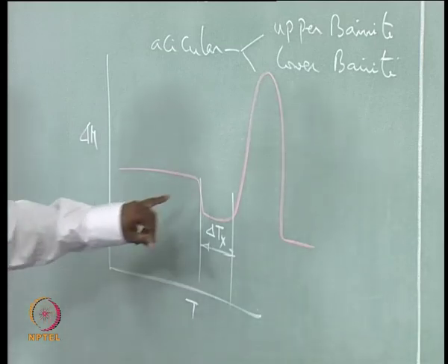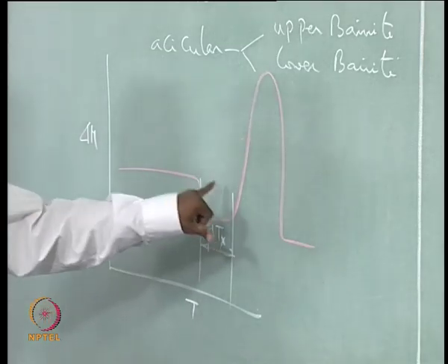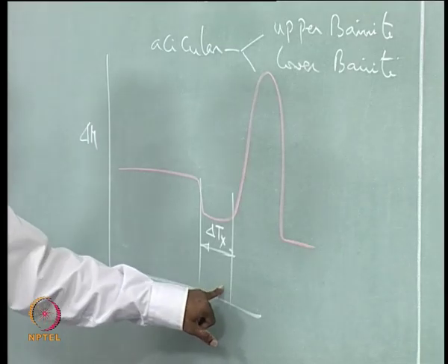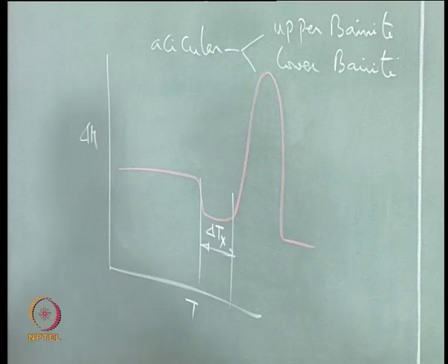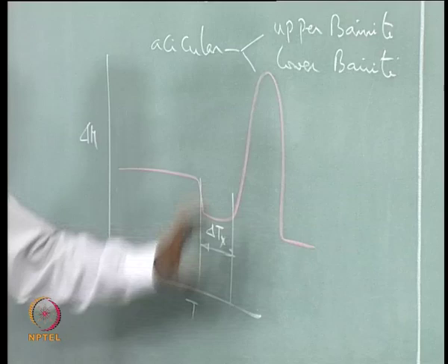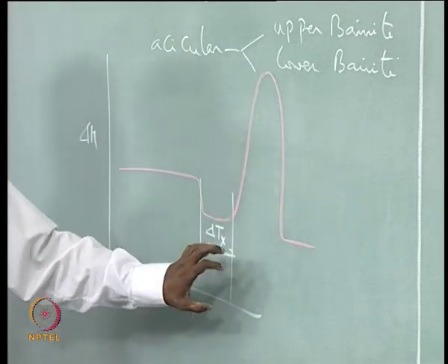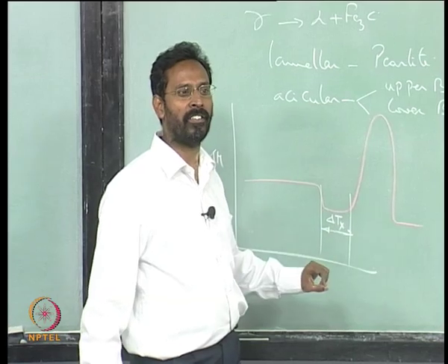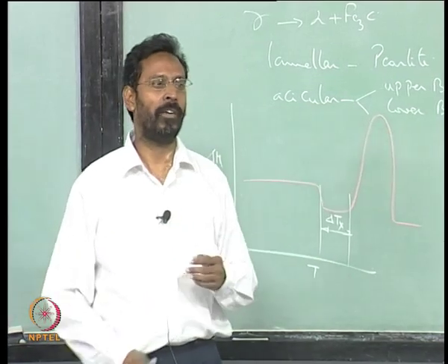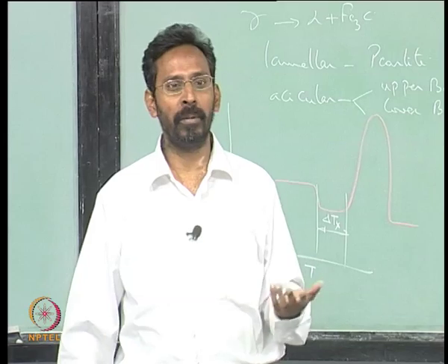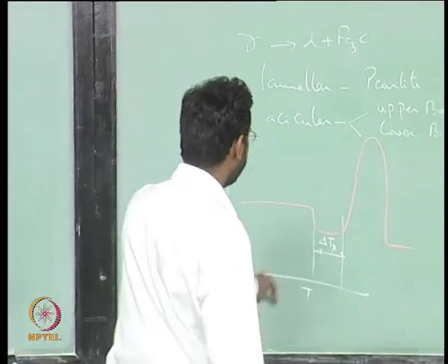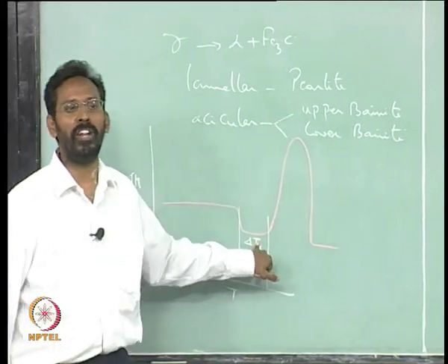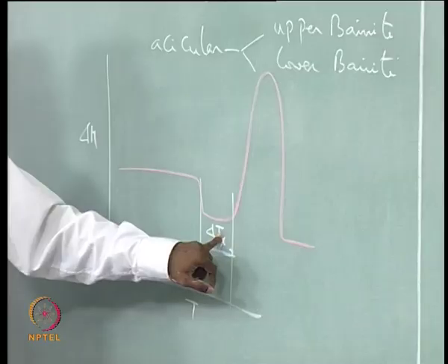Okay. So, where you have the glass is no more a glass, it has become a liquid, but the liquid is still remaining as liquid, it has not yet crystallized. So, it is like a liquid state. That is the reason why many people are doing a lot of deformation in this domain, metallic glasses, and then getting superplastic deformation. Glass, we all know it is brittle, but the same glass can be superplastically deformed if you are in this domain and get any shape that you want. So, many people do that.